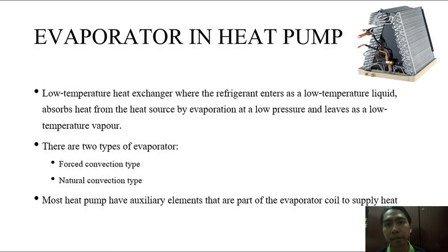Next is the evaporator. The evaporator is also an important component together with other major components. It acts as a heat exchanger that transfers heat from the substance being cooled to a boiling temperature. There are two types, which are forced convection type and natural convection type.